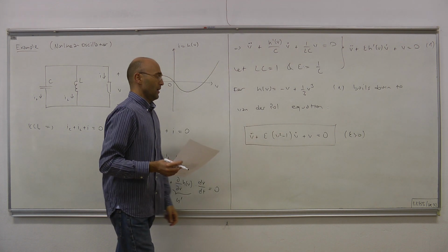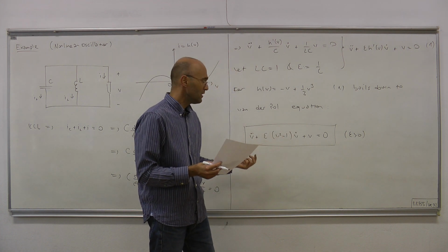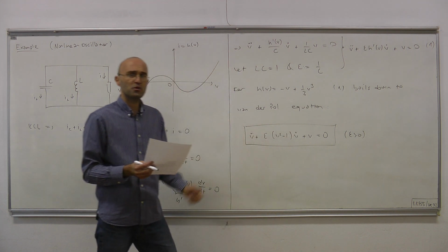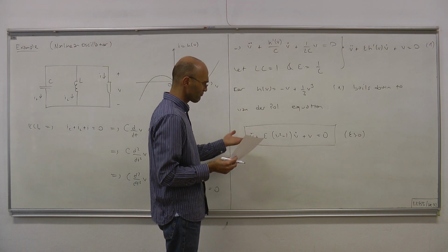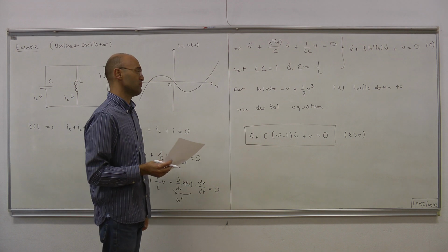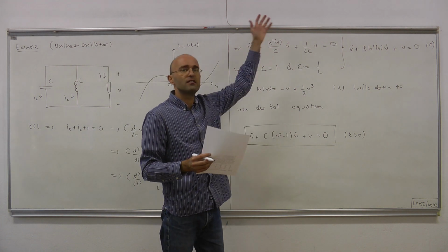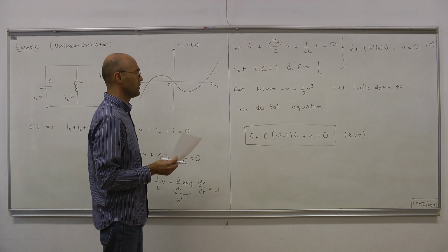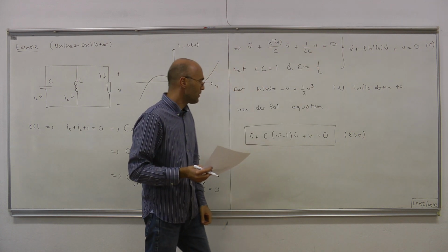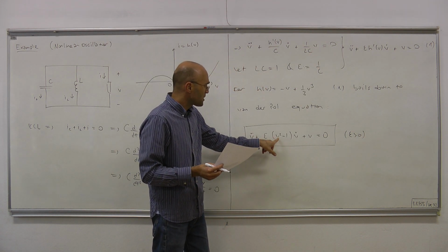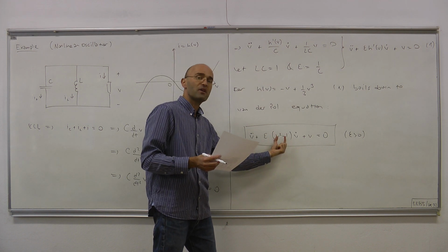The roots of the characteristic polynomial in that case would produce a positive eigenvalue, a positive pole, and that means the resulting dynamics would be unstable. That is, things tend to blow up, increase further and further. But as things tend to blow up, this guy becomes larger and larger, and it will dominate 1, and this thing all of a sudden becomes positive.